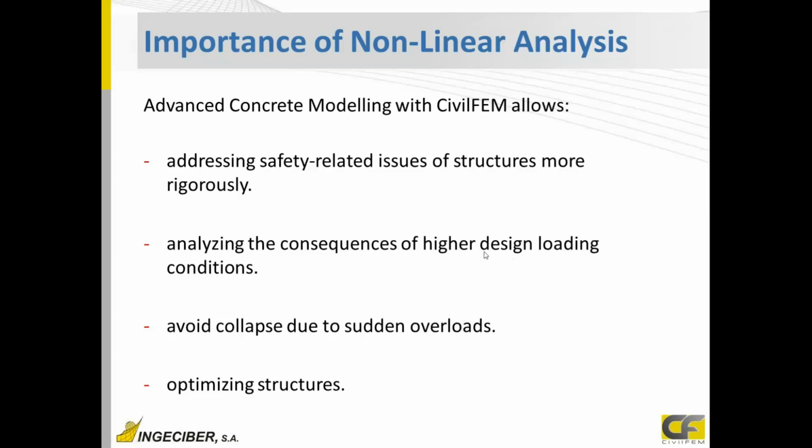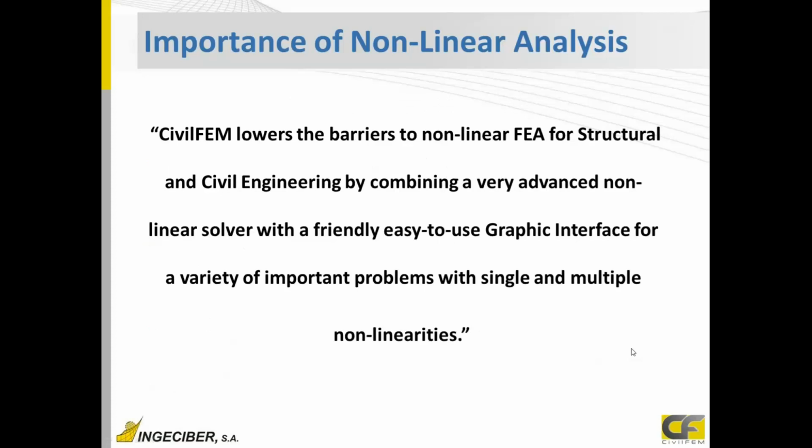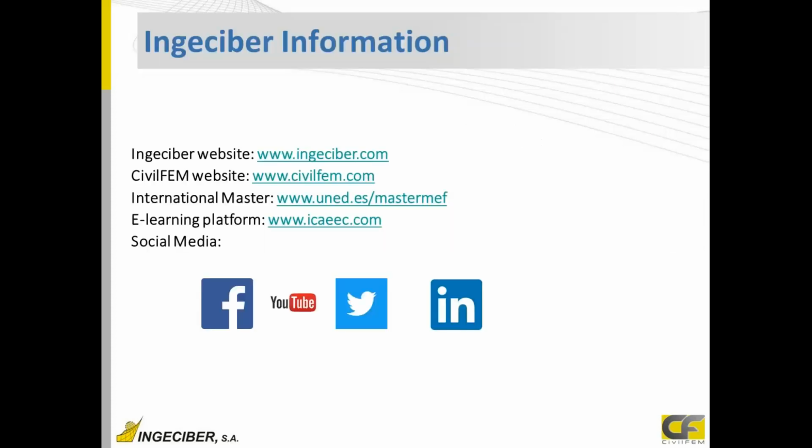Also, we can see what's happening with higher design loads, and whether it will suddenly collapse or keep a small remaining stiffness and ductile behavior. And in this way, we can optimize our structures. So with CivilFEM, you can see it's very easy to perform this nonlinear analysis, code and standard verification, any type of analysis.